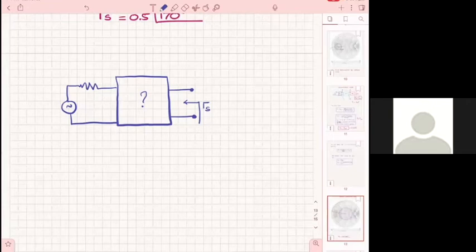When I look at the reflection coefficient, what do I do with the source? What do I do with the voltage source? You short it. Yes, why is that? It has to do with the Thevenin equivalent. Yes, so practically when I design gamma S, I'm looking for the input impedance here. Do you agree?